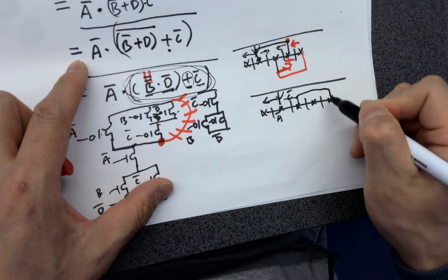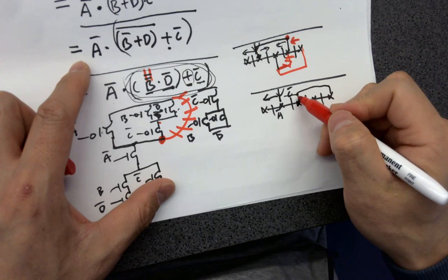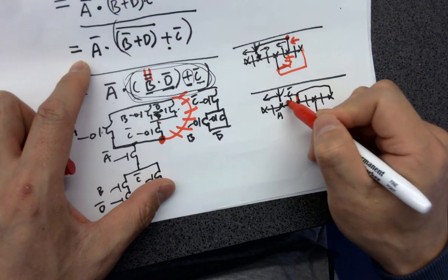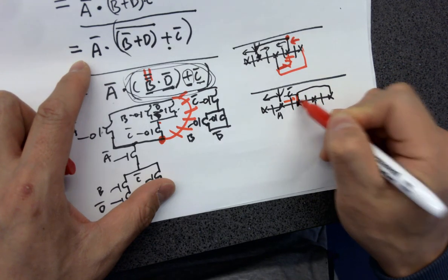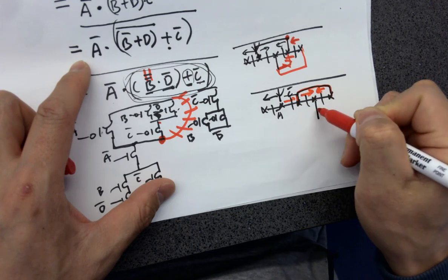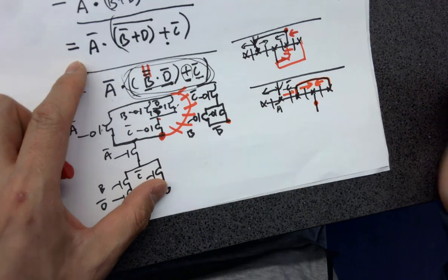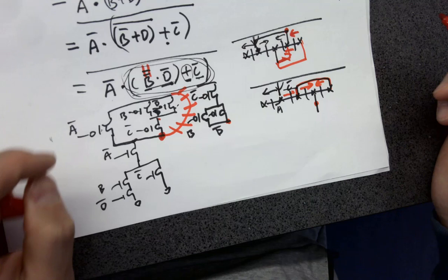And then I'm going to do a parallel transistor here. So whenever this one flows through C0, it reaches this node, and this is one node, so it's split into two branches and merges at this point. So this point becomes this point. So they're equivalent. So you can pass LVS.